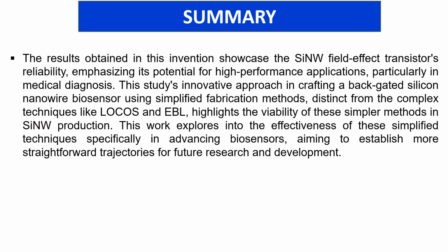So as a conclusion, our findings highlight the silicon nanowire field effect transistor's enormous potential and dependability, particularly in high performance applications like medical diagnosis. Our study is unique because of the creative method we used to develop a backgated silicon nanowire biosensor. We chose a simpler fabrication process instead of more complicated ones, such as e-beam lithography and ABL, which are commonly utilized.